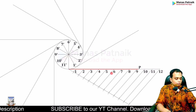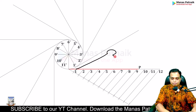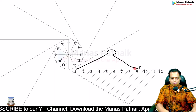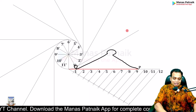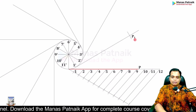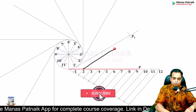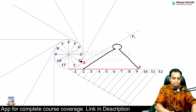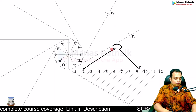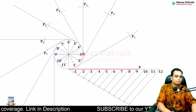So now what you need to do is, you need to keep the steel end of your compass at 1 and the pencil end of your compass at P. Now with this much as the radius, and with 1 dash as the center, cut an arc, and this is going to give you P1. Similarly, steel end of your compass at 2 and the pencil end at P. Now with 2 dash as the center, cut an arc again, this is going to give you P2. In the same fashion, you can mark the remaining points, P3, P4, P5, P6, P7, P8.